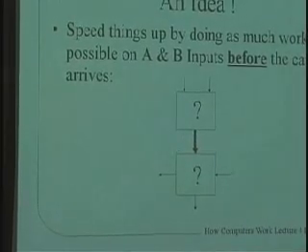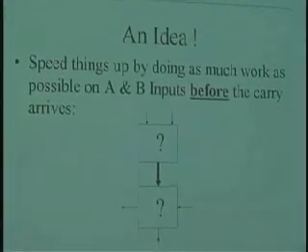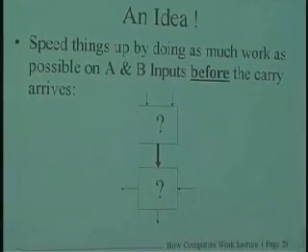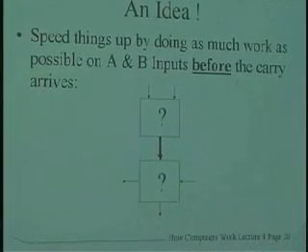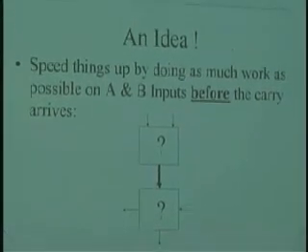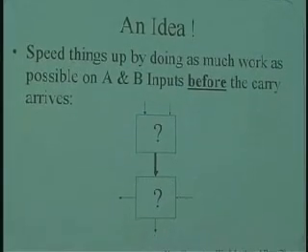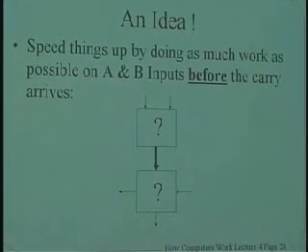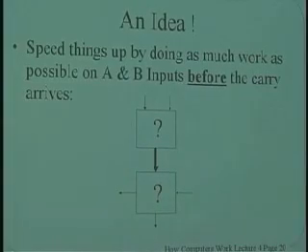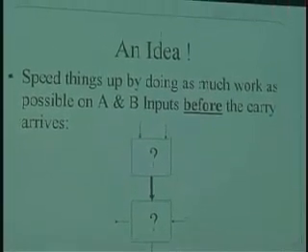So we see how we can implement sum using a parity tree like this, and we see how we can implement the carry out using a sum of products form that we can simplify by using a K-map. But still, we're left with an adder structure that's a series chain of these things and kind of slow. So let's talk about exactly what's going on inside of this adder and see if maybe we could speed things up a little bit.